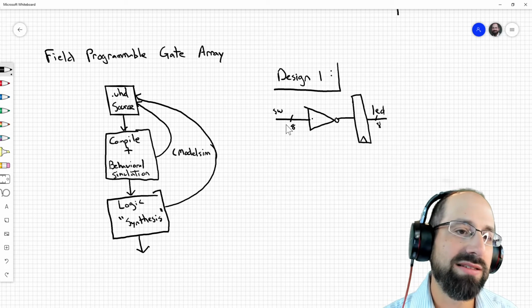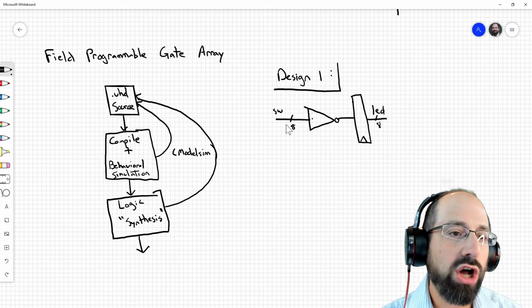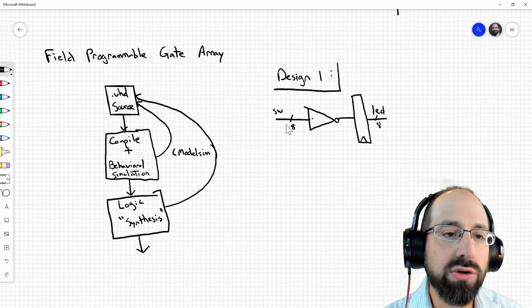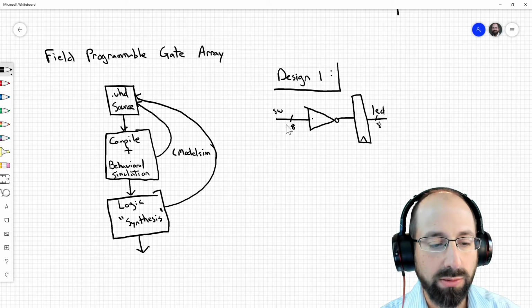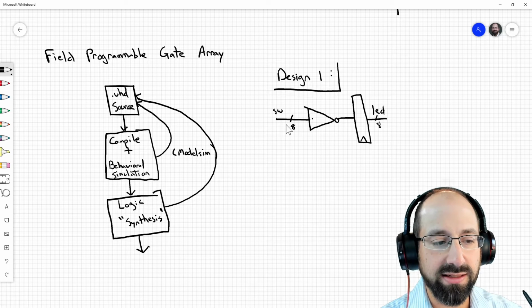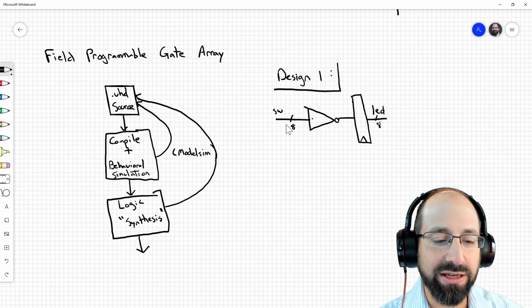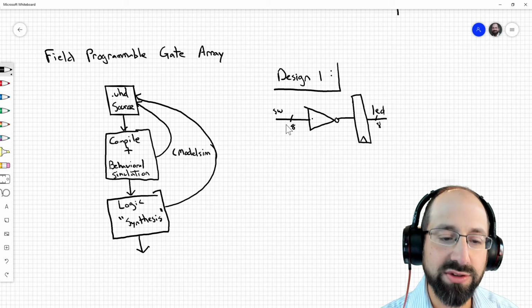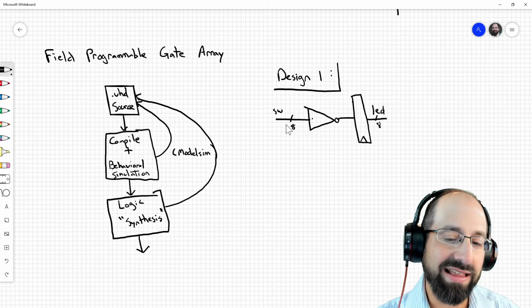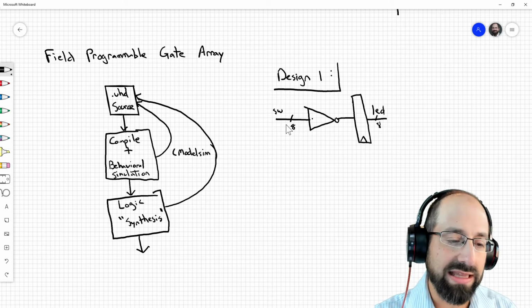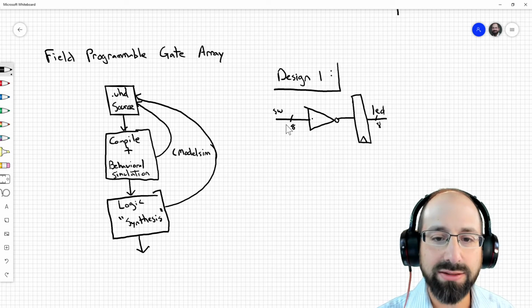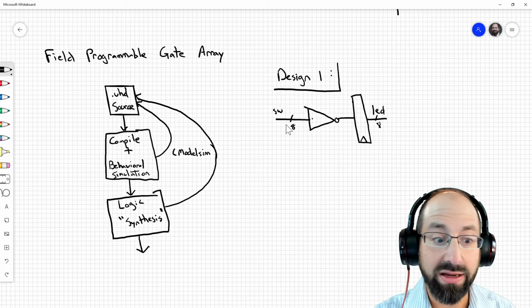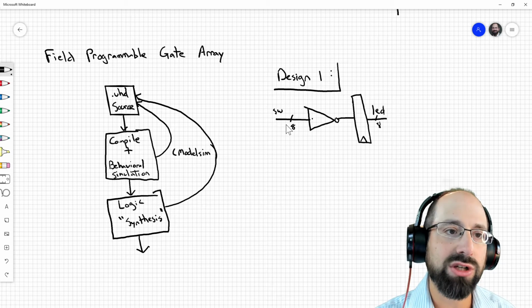We've seen that a lot with ModelSim as well. And we can actually also simulate this post-synthesis design. I find it's not that common that people do that. People are more comfortable analyzing the results of synthesis. But once you've gotten past behavioral simulation, you want to avoid doing lower level simulation, because it's at the individual gate level versus at a behavioral level. There's that many more signals. It's that much slower. Debugging and figuring out what you want to find is that much harder as you go.